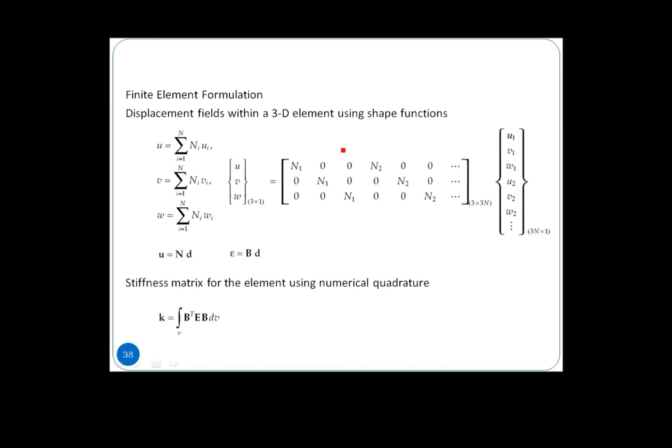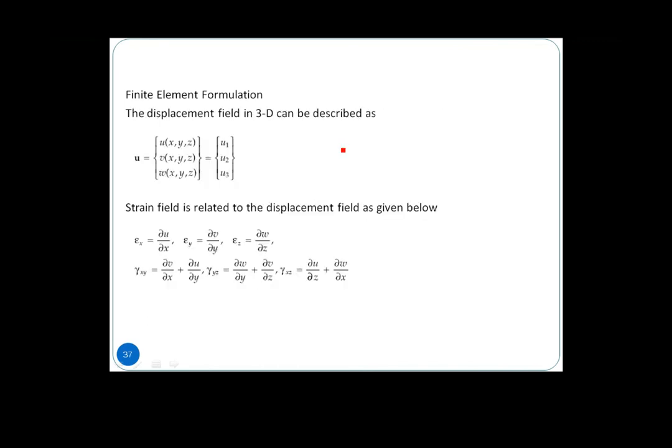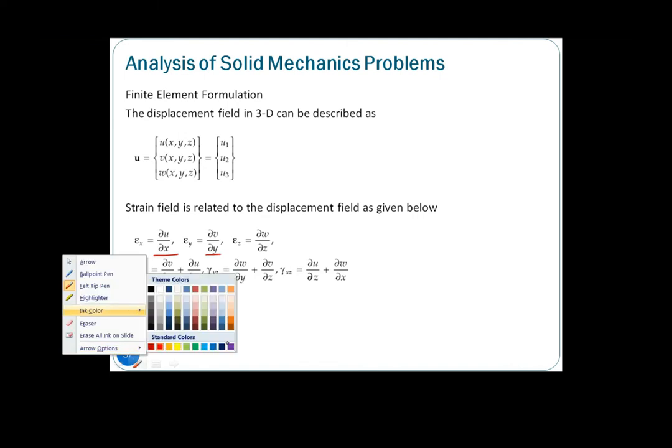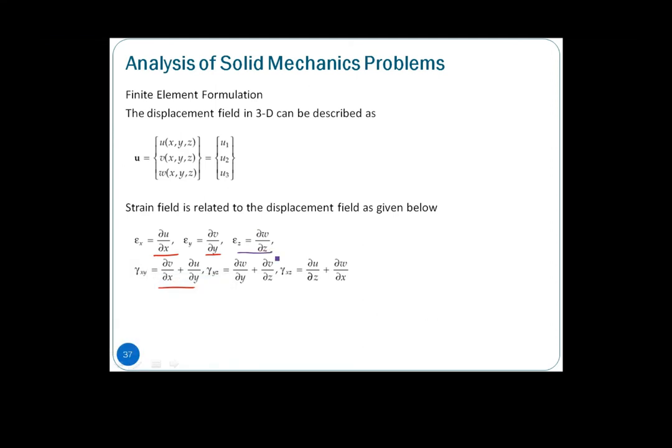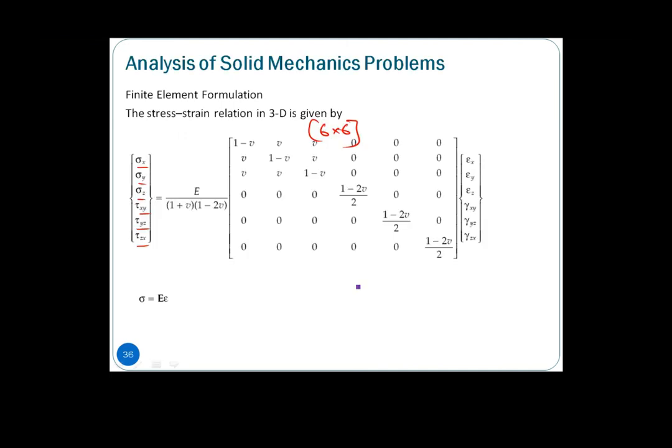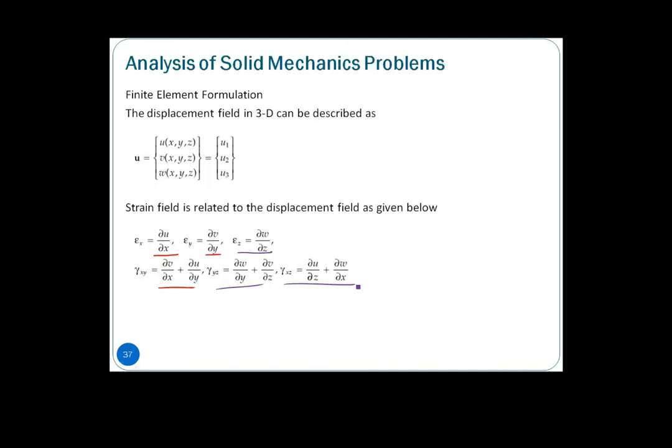So in terms of strain and also the displacement field, beside just now under plane stress, we are looking into these two plus this. So now we have to include the total state of strain, epsilon z, shearing strain yz, shearing strain xz. So a total of 6 components.